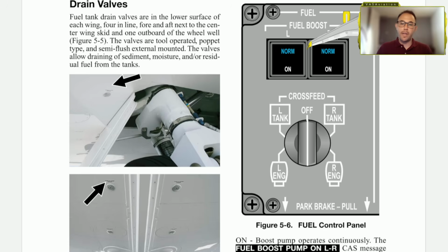So now imagine we have some delay on the flight, the passengers are not coming, or we have some other regulation delay, and we still have the APU running and the engines are still shut down, but we have the APU running and running for minutes and minutes. So we're only burning fuel from the right side.